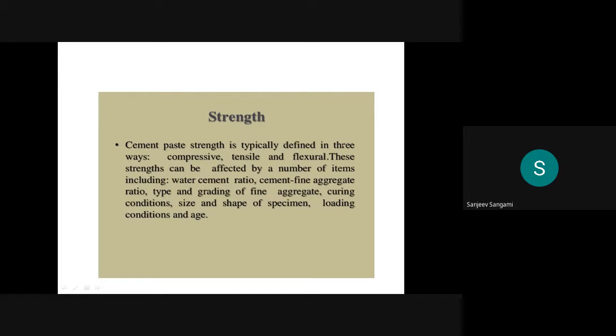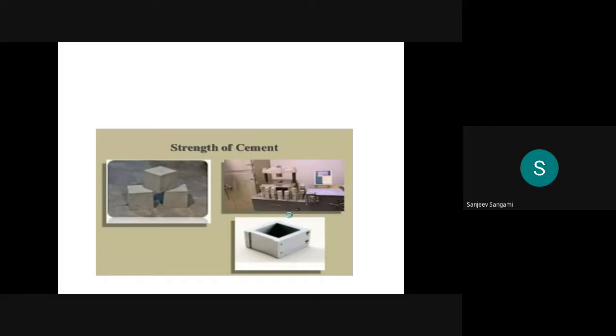These strengths can be affected by a number of items, including water to cement ratio, cement to fine aggregate ratio, type and grading of the fine aggregate, curing condition, size and shape of the specimen, loading conditions, and age. All these things depend on the strength characteristics.